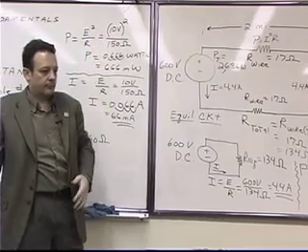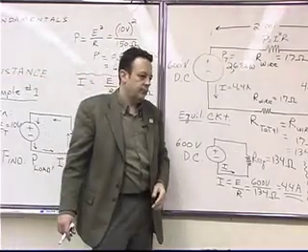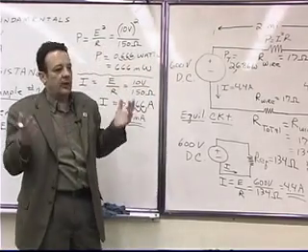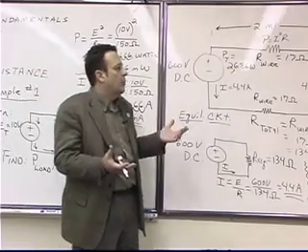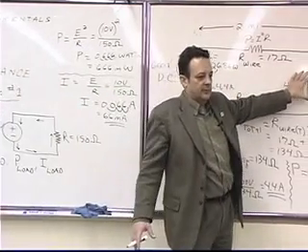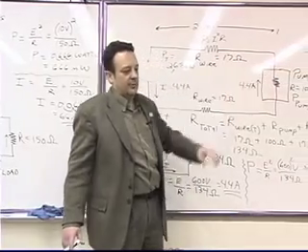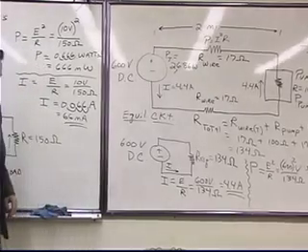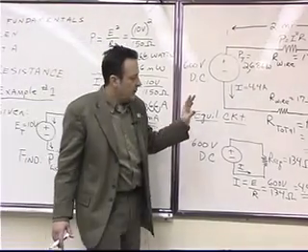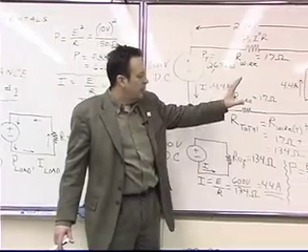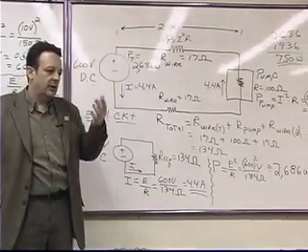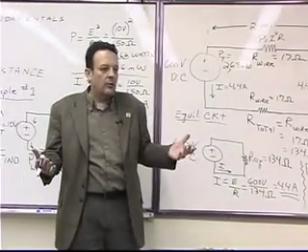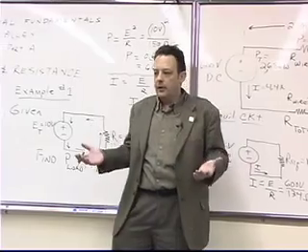And then do you have to dump it back to DC when you get to your pump? Well, it would depend. If we were sitting here designing this from scratch, we would probably buy an AC pump. Yeah, we would buy an AC pump. Then your inverter would be perfect. Right. But do you see how you can use the various laws of electricity and Ohm's law and series circuits to figure out, what am I going to do here? What's the best way to go?